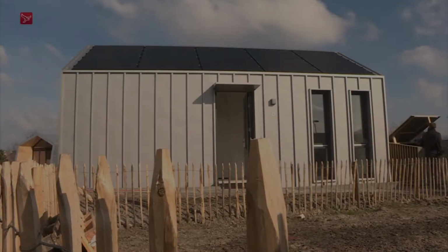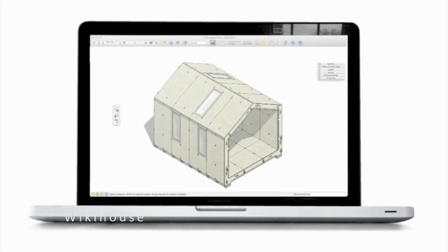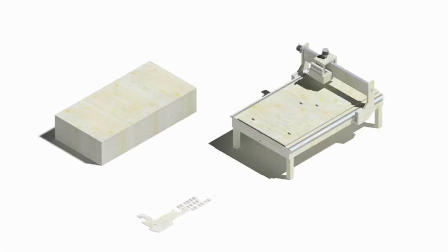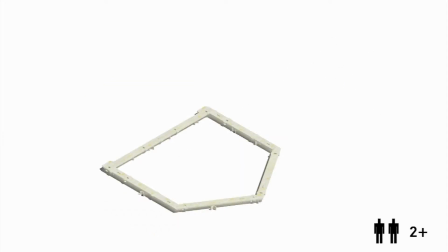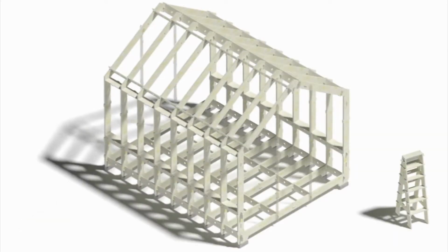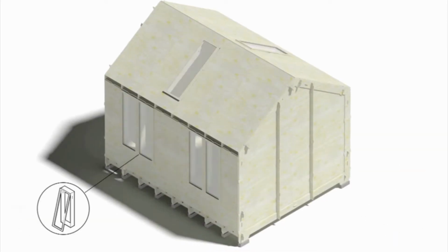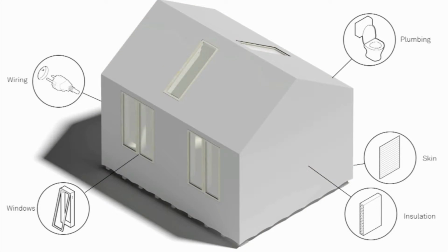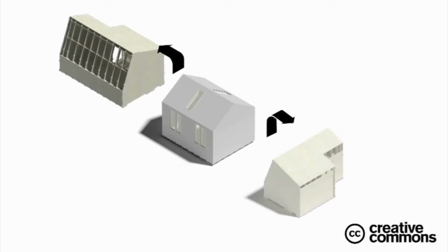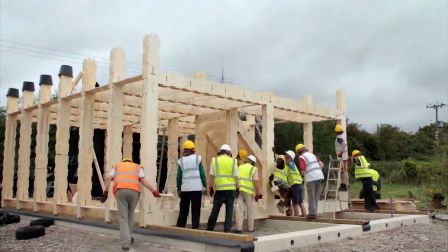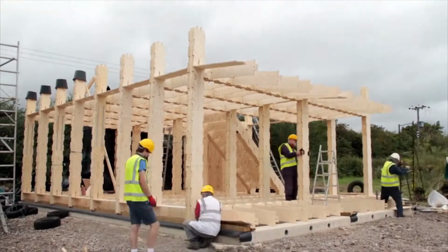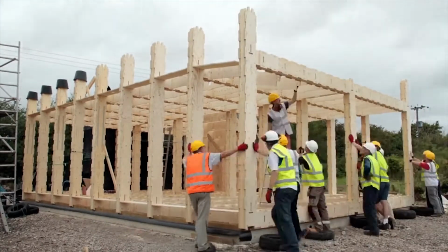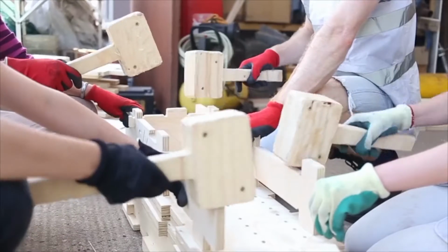The WikiHouse project demonstrates a new approach to prefabrication. The client gets a file with plywood details layouts, prepared for local digital CNC fabrication, and detailed instructions for assembly. The components can be rapidly assembled like a large flat pack by any able-bodied person, even without traditional construction skills. This example is notable for two reasons. Construction of WikiHouse structures requires no special parts because the cut pieces of wood snap together with wedge and peg connections. Thus, the project strategy determines the type of details.